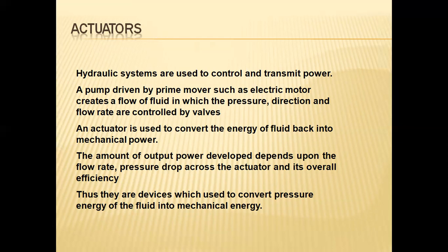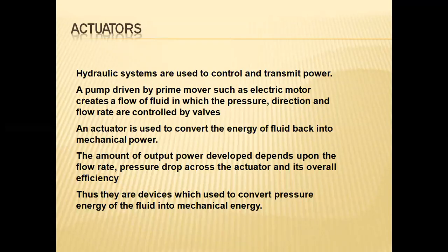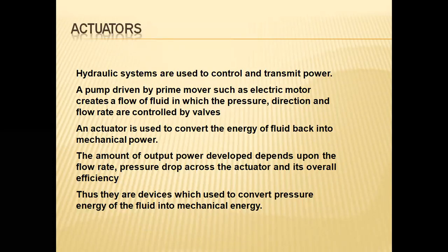To impart a particular pressure, the motor acts as a prime mover which creates the pressure in the fluid, and the directional control valves specify the channel through which the pressurized fluid moves, so that the actuation takes place in a particular direction, either in an extension stroke, that is a forward stroke, or a contraction stroke, that is a return stroke.